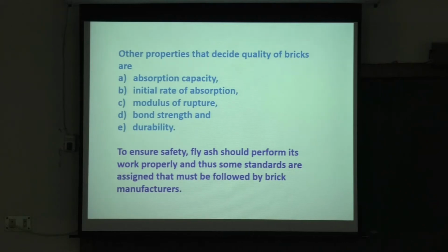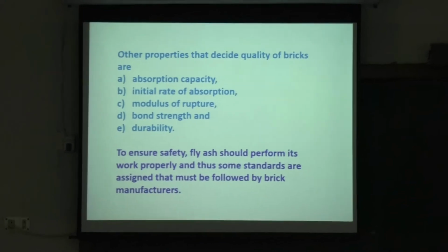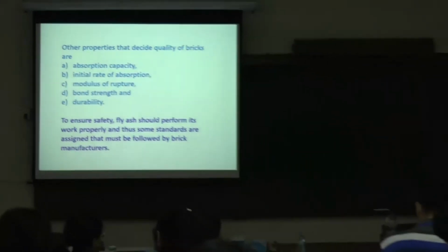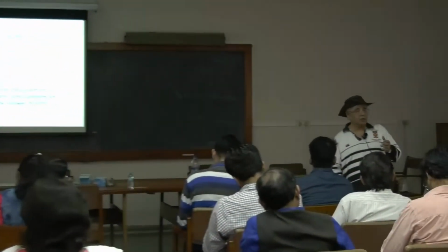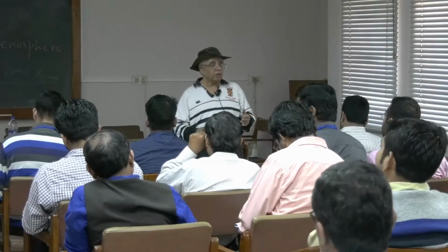But if you put in some small particles like short milled carbon fiber or even fly ash particles in the epoxy, that can make the epoxy tougher and stronger. If the epoxy does not crack, then the crack will not propagate through. Okay, so those are the areas where you can make composite structures tougher and better, and also cheaper, by using fly ash to improve the epoxy matrix. Okay, that's to answer your question.